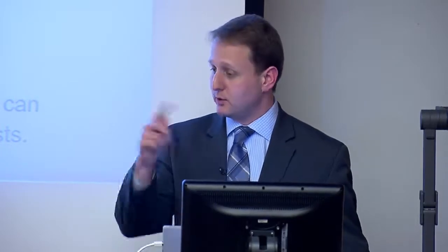Professor Lagerlof. So as you electroplate, you're consuming certain species. Do you supply them continuously? Yeah, typically in the industry, you would supply those continuously, either through a dissolvable anode or through a dosing pump that would be calibrated to the current flow. These baths run perpetually, right? So in a beaker in a lab, you run into depletion problems, but in the industry, the chemistry of the bath is held constant for years.